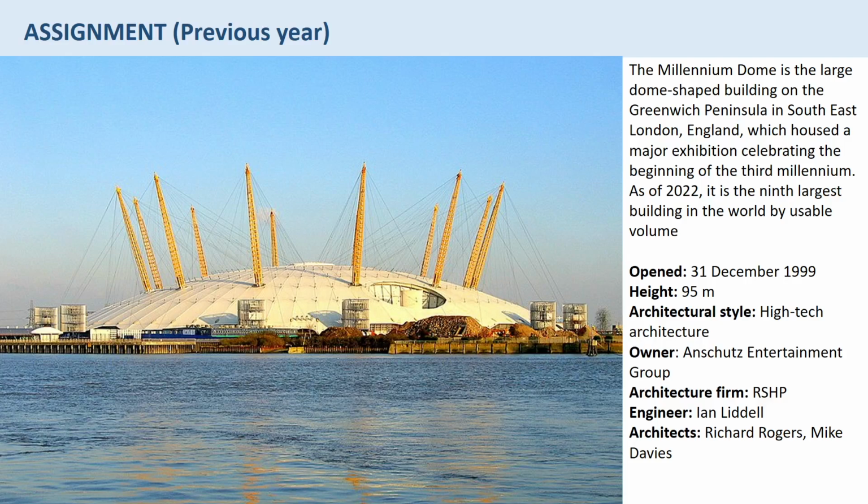Warren truss is another very popular truss system and is essentially identified by its construction from equilateral triangles. One of the main advantages of the Warren truss is its ability to spread the load evenly across a number of different members. Baltimore truss. The Baltimore truss is a subclass of Pratt truss. A Baltimore truss has additional bracing in the lower section of the truss to prevent buckling in the compression members and to control deflection. It is mainly used for rail bridges, showing off a simple and very strong design.